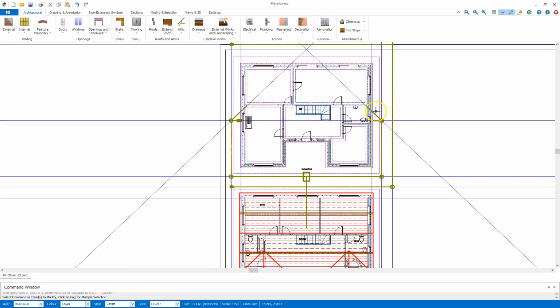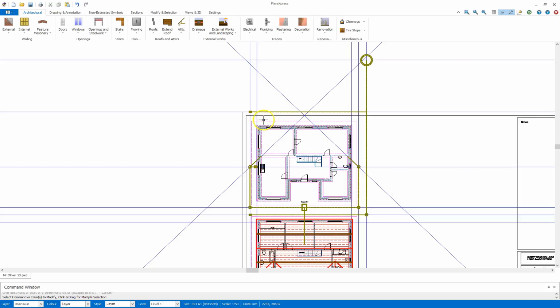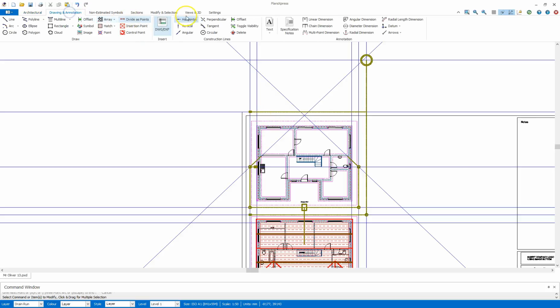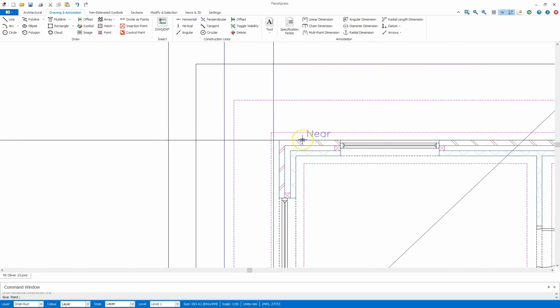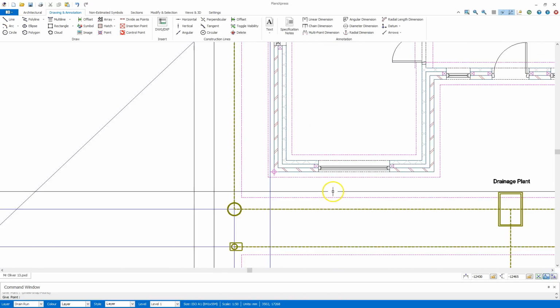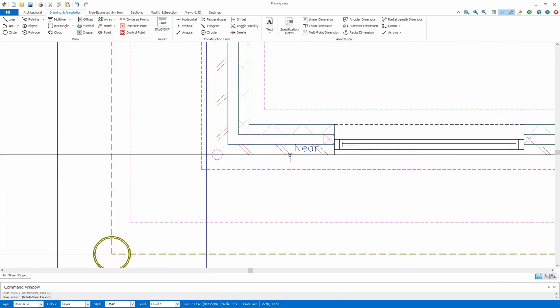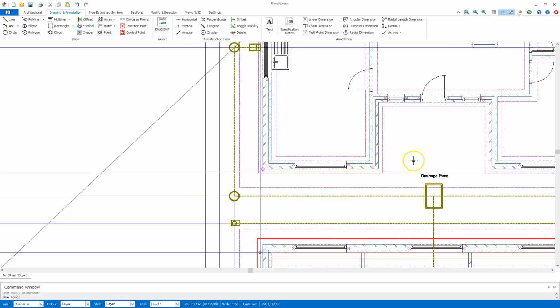Now that's the soil pipe, so you've got the waste link there, and we've also got the start of the water runoff from the roof. Now we need to actually link up the gutters themselves, so to do that I'm going to use some construction lines to give me some points to work from, placing the next stage. I'm going to hover over that wall there, press R, up 100. I'm going to come down to the bottom again, F7 to bring the snap back, R down 100. So on the corners of the building there.